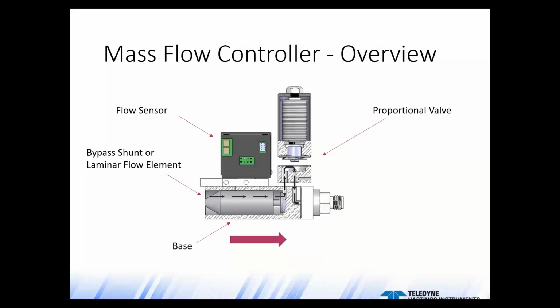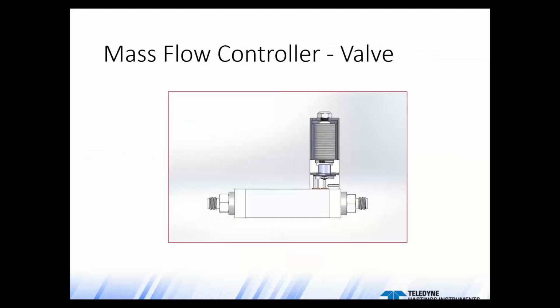Now let's transition to mass flow controllers. And before we discuss sizing, we're going to touch on the valve operation. Of course, the only difference between a mass flow meter and a mass flow controller is the addition of a proportional control valve. So all mass flow controllers include mass flow metering. But it will be helpful here to isolate the valve conceptually so we can look at the key components.